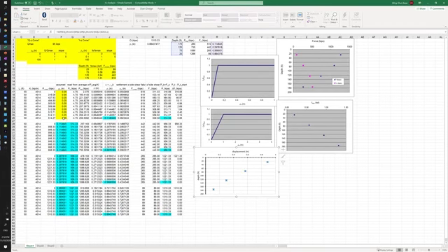So the smaller the thickness of each segment, the more segments that you have, the more data points that you will have to form this curve. So you fill up the gaps between those points over there. If you use, instead of 50, maybe 25 thickness of each segment, then now we have 8 segments instead of 4 segments. But anyways, this is how you get the displacement curve from the TZ analysis, and it gives you all the numbers you need: both the elastic compressions, side frictions, and also the base settlements.